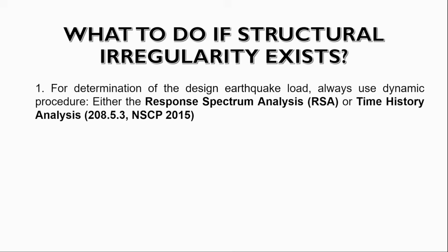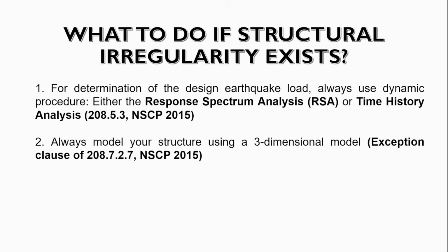I will not discuss response spectrum analysis in more detail here, but you can do it on your own. I'm just discussing the different irregularities. Next, it's good that we use a three-dimensional model. We can design our structure in two dimensions, but especially if we have horizontal irregularities, we should consider a three-dimensional model partnered with the dynamic procedure. There is also an exception clause, but we should just use a three-dimensional model.